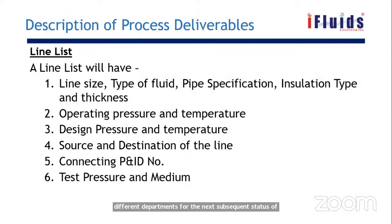Line list. There will be a number of lines in the plant. So we need to make that list, and that will be useful during the commissioning stages. The line list will be provided with the line size, type of fluid, specification, insulation type and thickness, and then all the operating conditions, design conditions, and then the source and destination, from which equipment to which equipment it is coming. Because only the process team knows the details, other disciplines may not know.